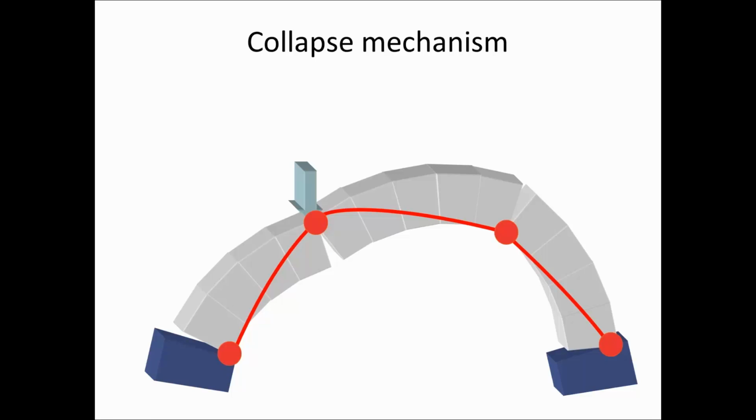Similarly, and this is relevant to today's webinar, if the abutments, for example, were to move relative to each other, for example, outwards or inwards, again, that means that we can have knowledge about the line of thrust, so it's uniquely determined, and hence we can gain an understanding of how the load is transmitted through the structure.